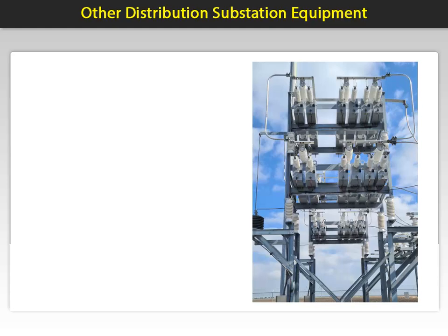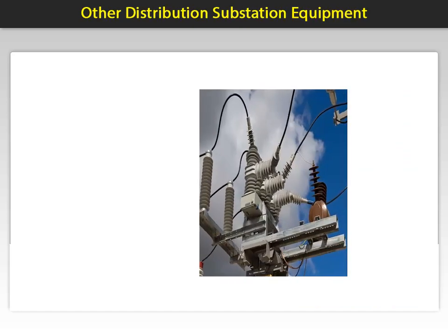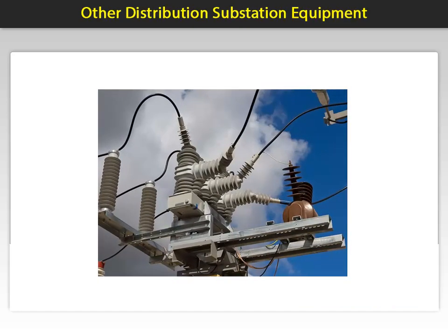These are supplied in outdoor cabinets or in overhead racks as seen here. Reclosers are equipped with smart or overload sensors and electronics specially designed to protect the power grid and the customer, automatically isolating the error and recovering if the defect has been corrected. The recloser senses when trouble occurs and automatically shuts off the power. A fraction of a second later, the recloser turns the power back on, but if the trouble is still present, it shuts it off again.